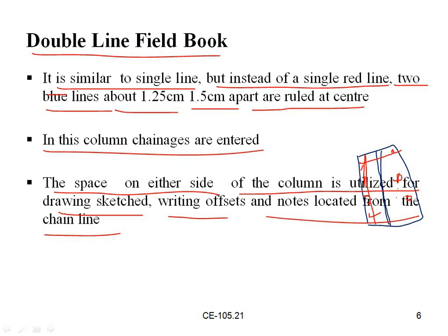These field books are compulsorily used in surveying, because whatever measurements we are taking, we should not write in any notebook or rough book. If the field book is there, the measurements can be understood very clearly. This is the so-and-so measurement we have taken, and if the diagram is also drawn in the field book, it is easy for understanding.